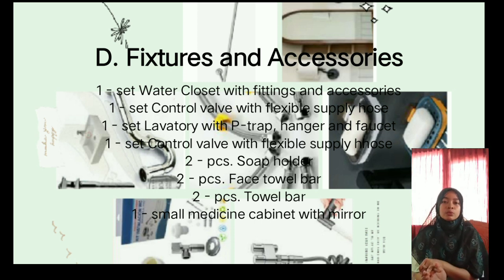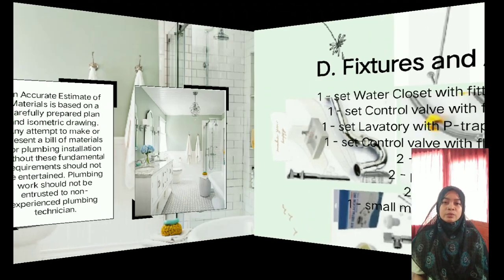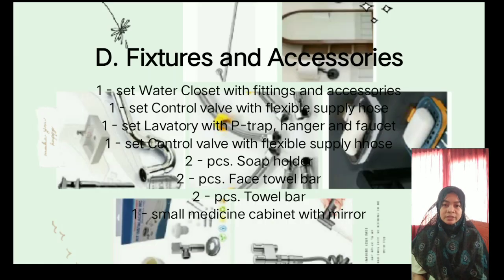It is also important to plan the layout to ensure proper spacing and accessibility. Second is to install water supply lines. So shut off the main water supply. Also install shut-off valves on existing water lines if not already present. Then connect the water lines to the appropriate fixtures using compression fittings or soldering, depending on the type of pipes to be used.